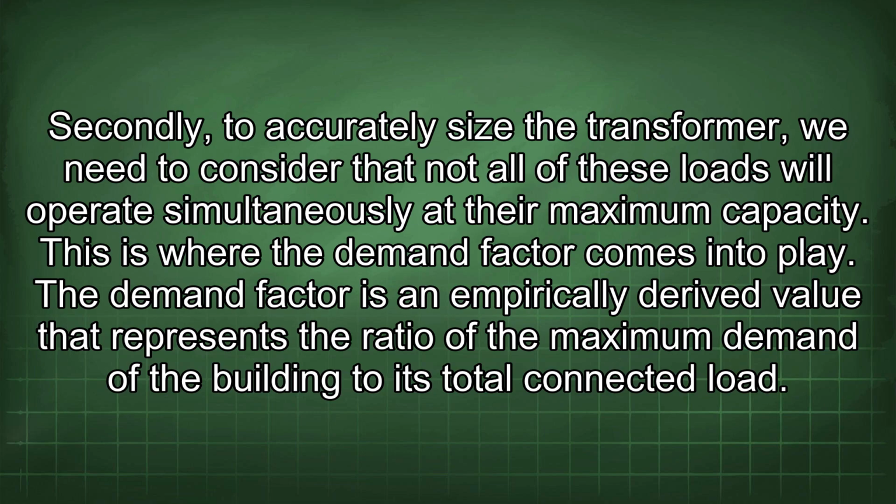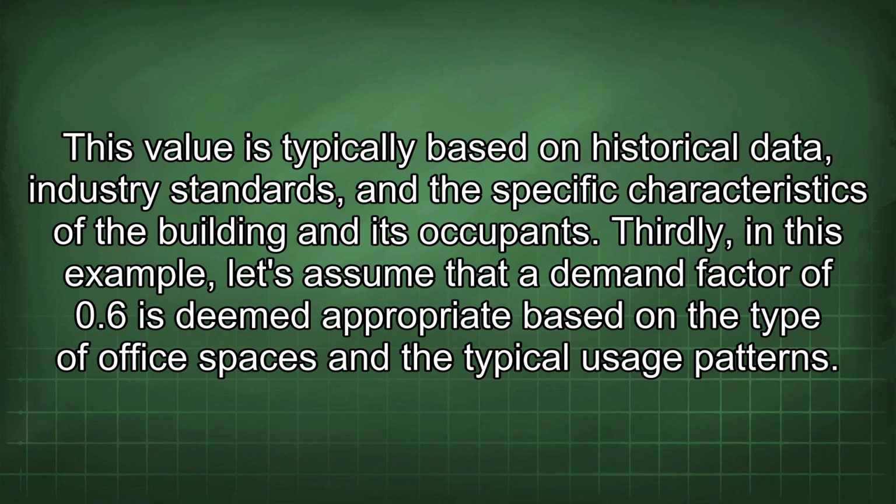Secondly, to accurately size the transformer, we need to consider that not all of these loads will operate simultaneously at their maximum capacity. This is where the demand factor comes into play. The demand factor is an empirically derived value that represents the ratio of the maximum demand of the building to its total connected load. This value is typically based on historical data, industry standards, and the specific characteristics of the building and its occupants.